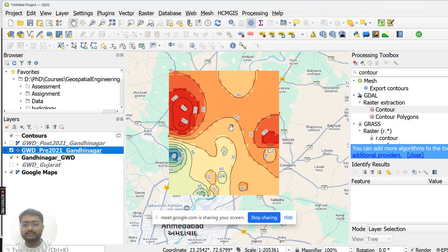It's not changing in between. If the value is between 60 to 70, it will show just one color only, not multiple colors. And you can see, when we are converting this raster data to vector data, this generalization is not proper, or you can say the conversion is not capturing the entire boundary with a smoother line, because this is the loss which we are getting.